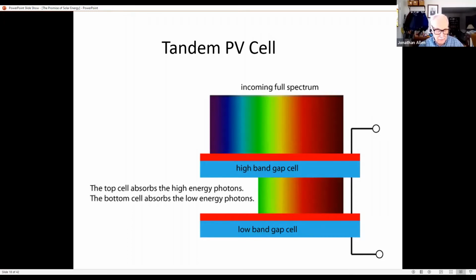Now let's look at some of the other limitations. Since real photovoltaic installations do not enjoy constant direct sunlight all day, they can exploit two forms of tracking. The first is a power conditioner or inverter that constantly adjusts the load on the array at its peak power point. The second is sun tracking.